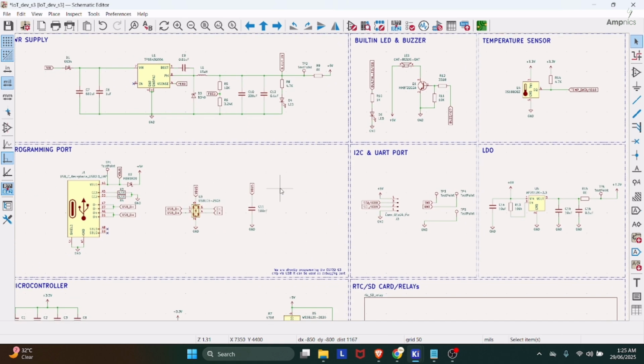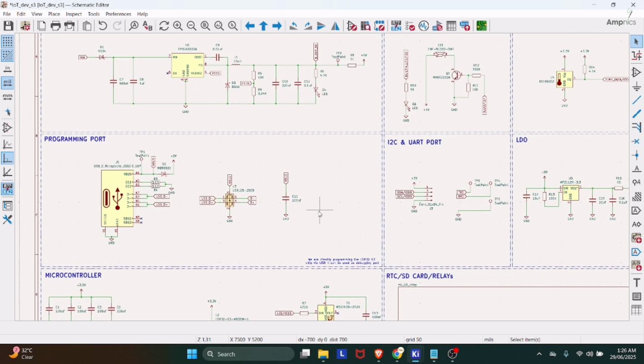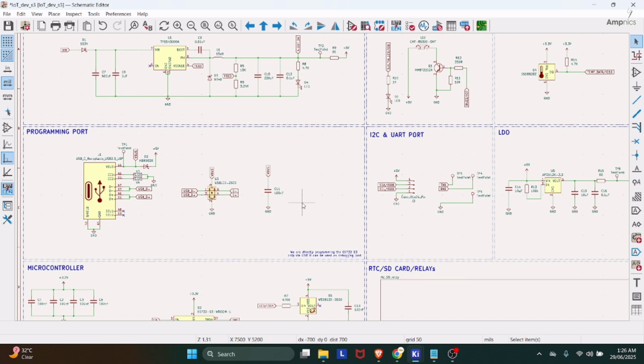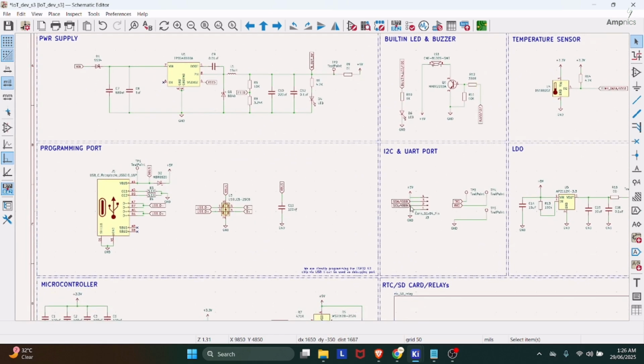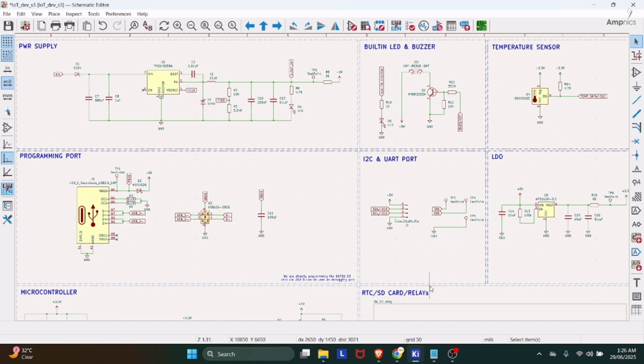If you just start adding components one by one and you go for large production, it will definitely cause a high cost. If a part costs about $0.1 and you're going to produce 1 lakh units, just multiply that $0.1 by 1 lakh units. So your production cost is going to be high. You have to take care of everything according to your application. As of now our application is not that crucial, so for that reason we can also ignore the ferrite bead.